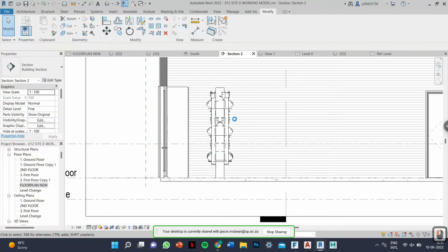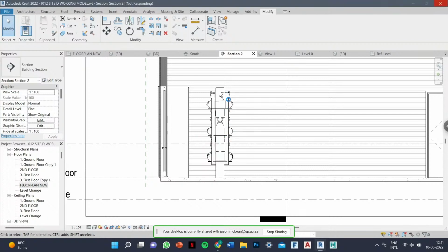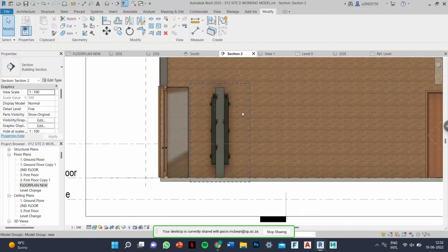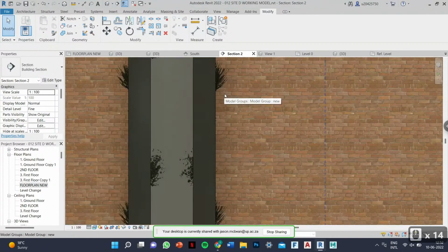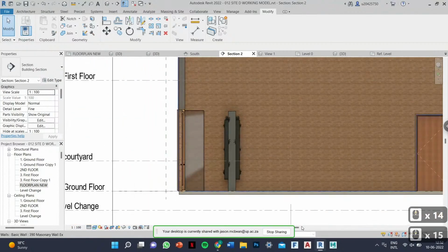So I usually don't put these things in Revit like this, because the only time you actually see them is when you're rendering. For this exercise, I could have put those plants in Twinmotion a lot quicker. So for these plant things, I'd create the frame where the plants sit, but not put the plants in. You just create the wall with the openings. Because now you'll see the plants, but only in this render view.